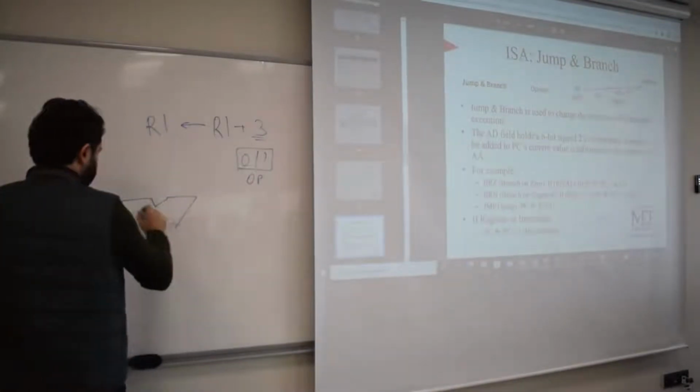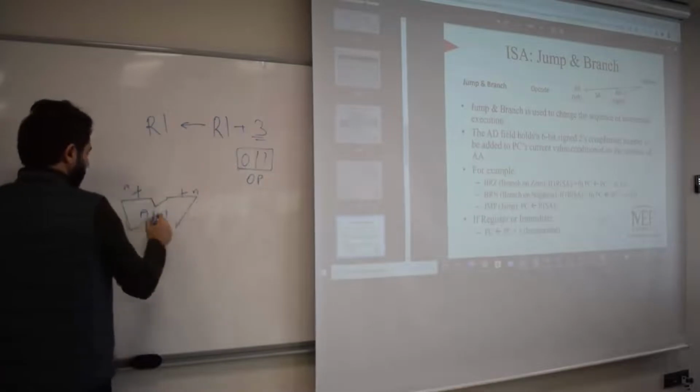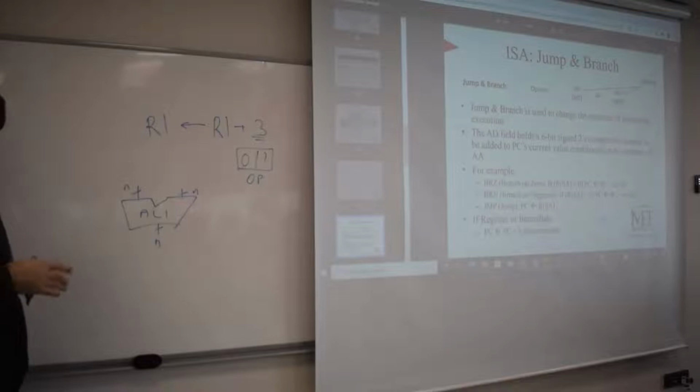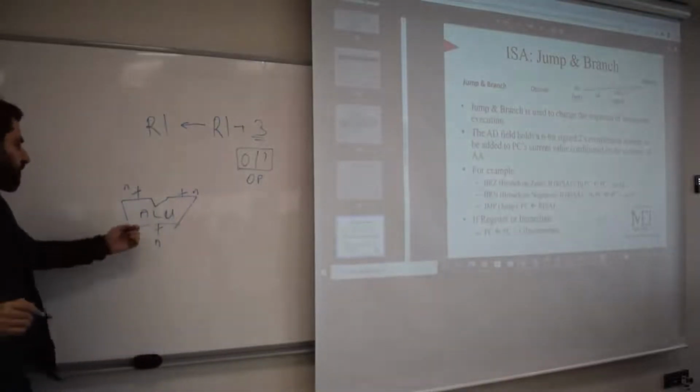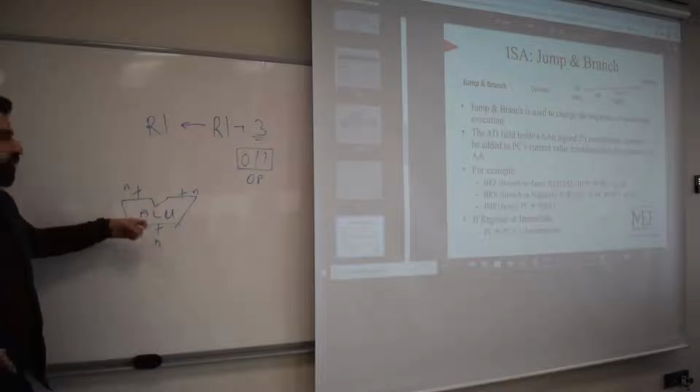ALU is something like this. It accepts two n-bit numbers, and then it generates another n-bit number. It's an n-bit adder, for example. But of course, we want more functionality in the ALU. We add extra stuff here, like just with a simple set of XORs, we make it subtraction, right? And then we can also add extra logic operations.